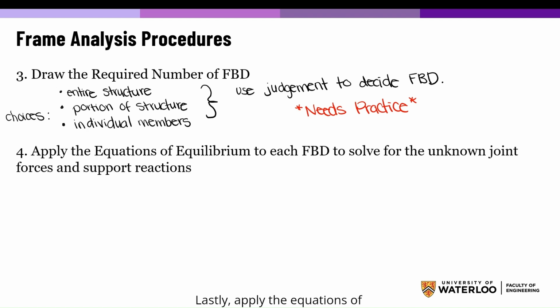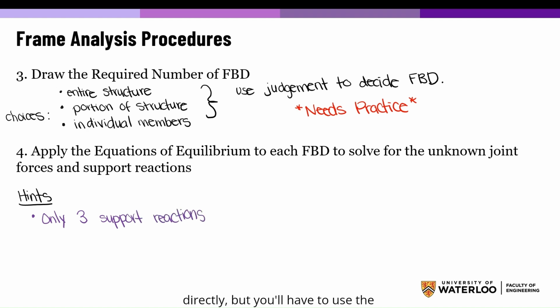Lastly, apply the equations of equilibrium to each free body diagram to solve for the unknown joint forces and support reactions. So recall that you may not be able to solve for each force directly, but you'll have to use the system of equations to solve.